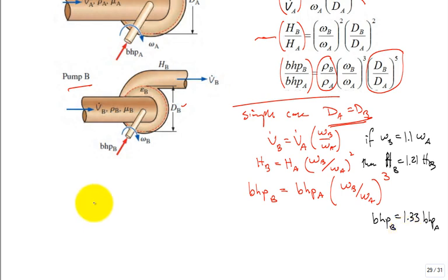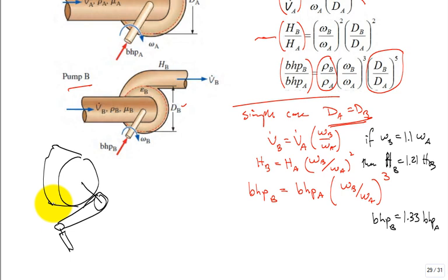So typically, you have a motor, and the motor comes out and there's a pulley. And the pulley goes to a belt that drives another pulley, and that pulley is connected to a shaft, and you have a great big squirrel cage blower, an air handler, to move air. And so the air is ingested into the eye region, and then it's blown out that way.